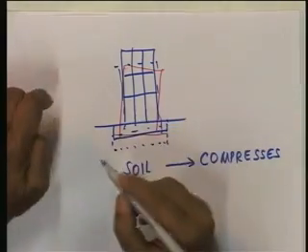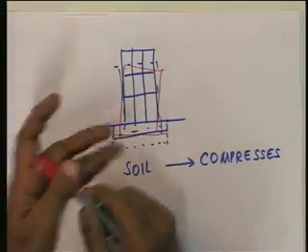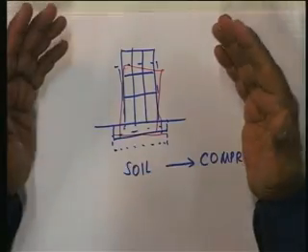When it tilts, it may still remain in equilibrium, maybe momentarily, but if the non-uniform part of the settlement goes on increasing with time, then the building is definitely not going to be in equilibrium, it is going to undergo tremendous distress, which will manifest itself in the form of cracking of the building, cracking of its beams and columns, and in general disrepair.